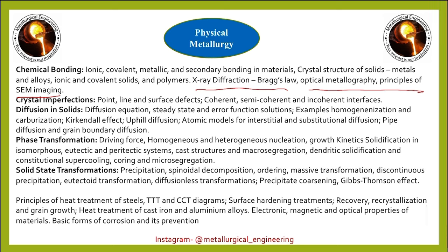Then you have diffusion in solids, in which you have the diffusion equation, steady state, and error function solutions. Examples: homogenization and carburization, Kirkendall effect, uphill diffusion, like that. And then comes phase transformation, in which you have homogeneous and heterogeneous nucleation, growth kinetics, solidification in isomorphous, eutectic, and peritectic systems, cast structures, microsegregation, dendritic solidification, constitutional supercooling, and coring.